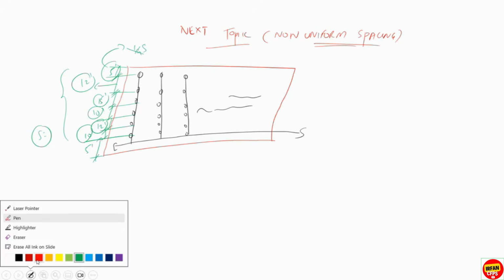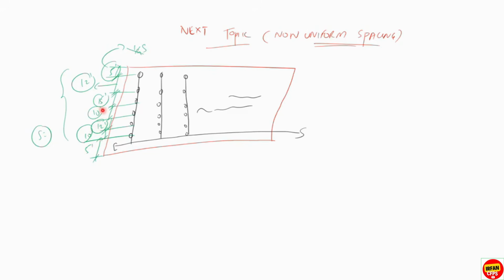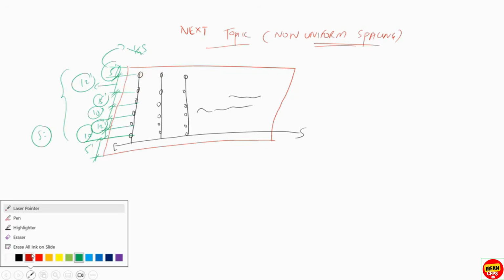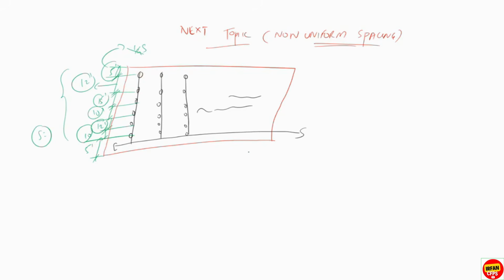So based on this, 10 feet, 12 feet, 10, 15, 12, S is different, right? Along the branch line is S, between the branch lines is L, right? So now the concept varies. Now, the length of the design area, this is fine. The first step is fine. Length of the design area is 1.2 times root of design area. This formula is fine.